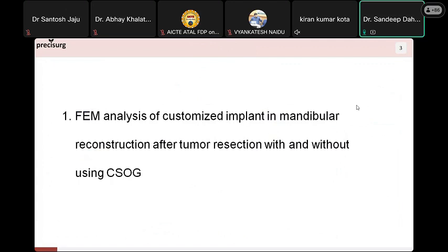So you can see in figure 1, in the loading and boundary condition, we have taken around a 46-degree angle with the surface because maximum load is applicable in this particular condition. So we have given around 554 Newton load, that is the maximum load, which the data has been taken from the previous literature, and performed a finite element analysis.